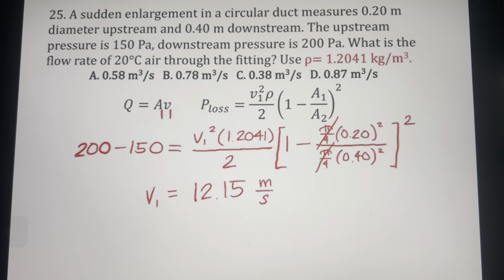Our formula in this problem is M times the quantity of Cp of water times the change of temperature of water plus the latent heat of fusion plus Cp of ice times change of temperature of ice. Okay, our Q is equivalent to M is 2,000 kilograms multiplied by the Cp of water is 4.187.